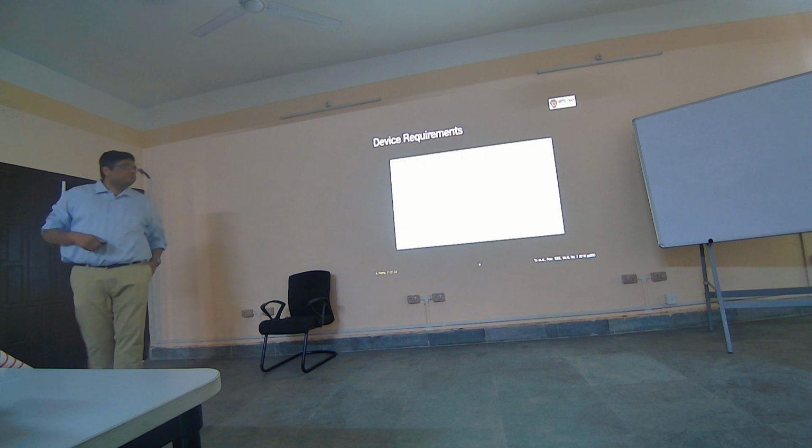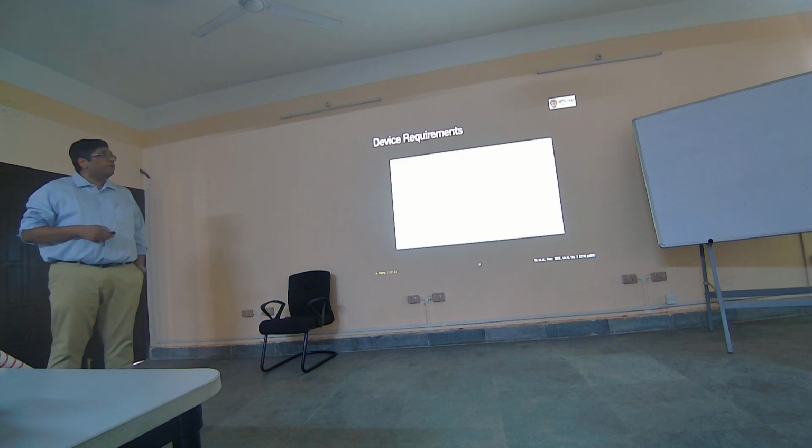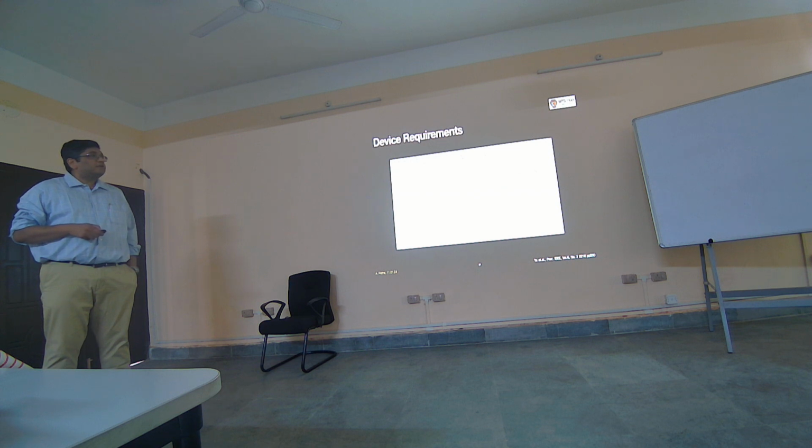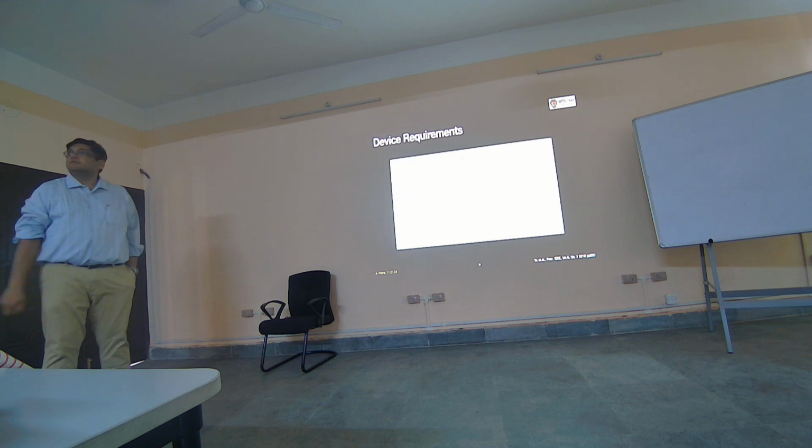So this roughly just puts the numbers out for you. Device dimension around 10 nanometers, multi-level states, ideally up to 100, so it becomes analog. Energy consumption of roughly 10 picojoules. Dynamic range around the same, and retention and endurance.